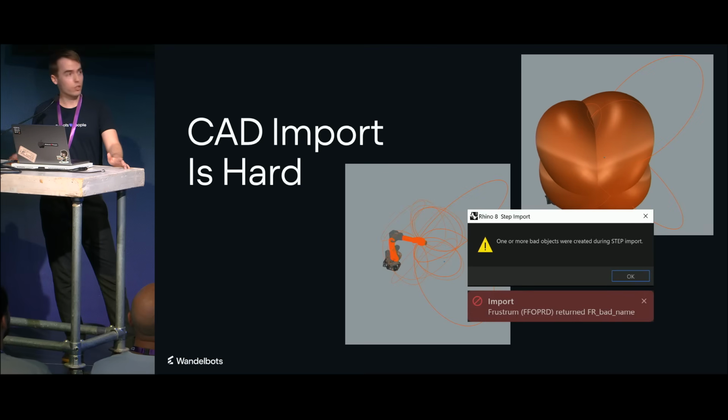These models are not just for visuals, they must be accurate. We need the precision for colliders that we create with our robot models, so the robots don't collide with themselves, link for link, or with safety zones, or even humans. That's why we always use manufacturer models directly, never pre-modified ones from some sort of marketplace, to preserve this accuracy.